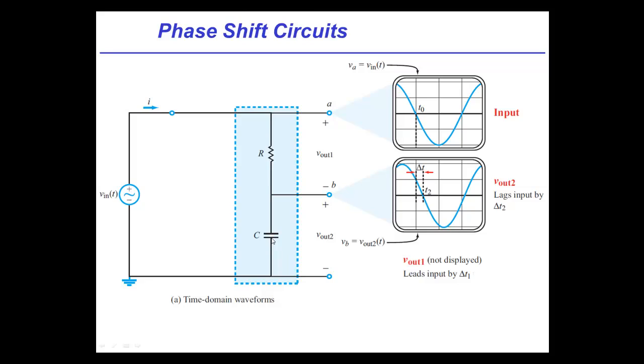Let me ask you a question, Michel. Let's say I wanted to have a capacitor in there, but I wanted the current to be in phase with the voltage of the source. Oh, that's sneaky. You're jumping ahead. All right. How might I do that? Well, then I basically would want to add an inductor to that capacitor in series so that the inductance and the capacitance, essentially those two impedances cancel each other out. Exactly. I would pick them such that the 90-degree lag and lead contributed by each one exactly cancel. Okay. So they'd have the same magnitudes, and the net result would be the current and voltage would stay in phase. I have a suspicion some other interesting things happen if you do that. Yep. We'll get to that.